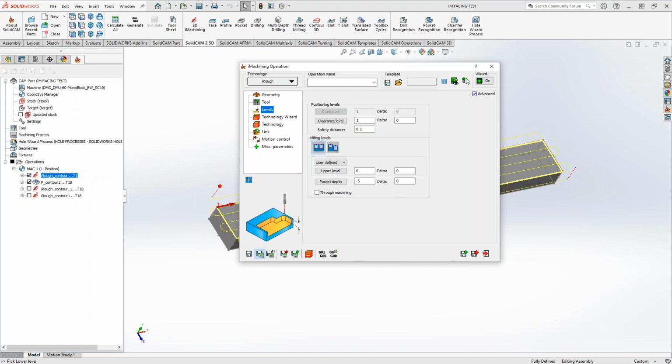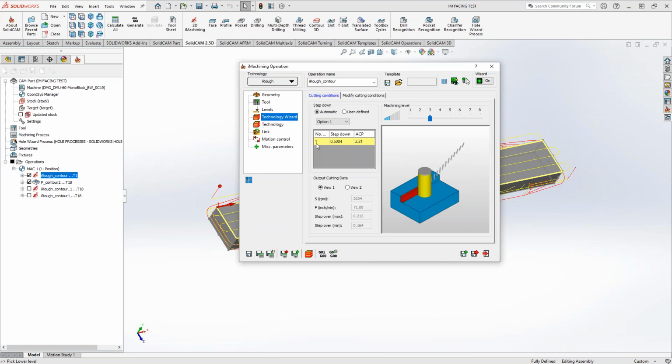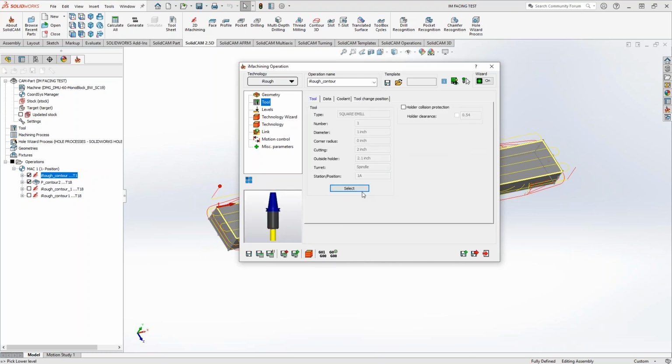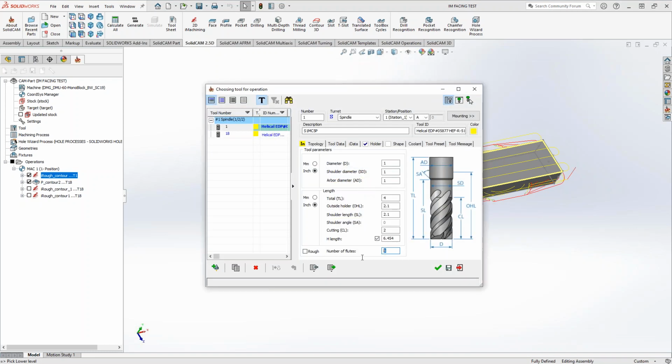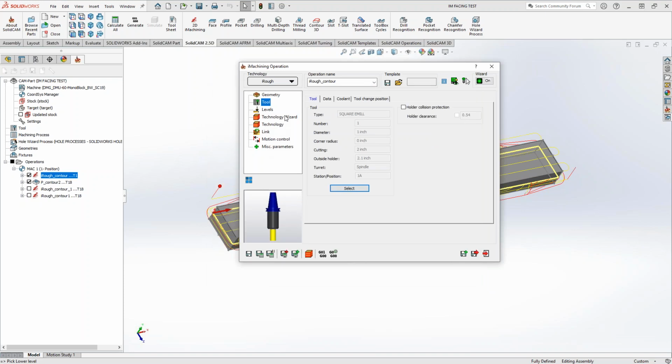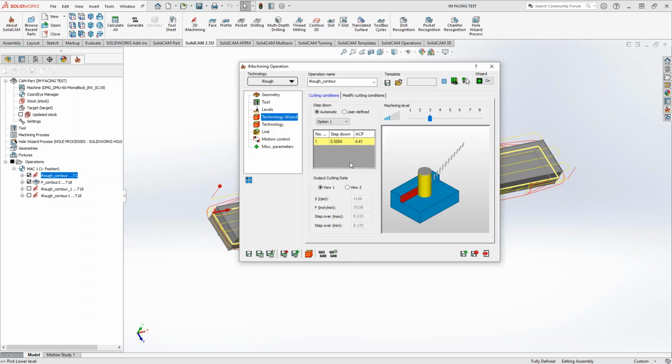And we could get that tool to be ideal, but like Mark said, it's going to be really small with a lot of flutes, just because it's such a light little cut in there. So now we're getting into the yellow range. Now we can add a different, smaller tool in there. We can go with more flutes. Just to show you guys, if I kick this up to not a realistic tool, but say 16 flutes, oh, we're still not in the yellow. So it's still not the ideal tool for the cut, even though we have 18 flutes.